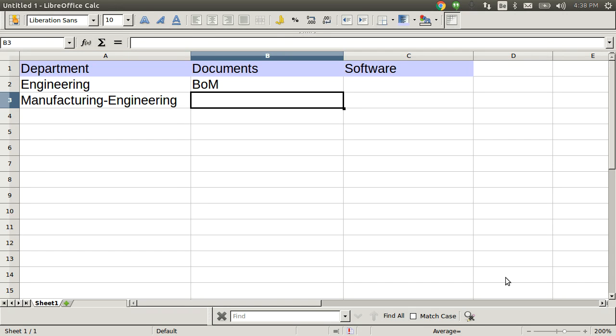Those guys are responsible to design the manufacturing line. So once we have the plan, we know how to build the piece. We have a department that has to buy the machine, set up the machine environment, and decide how the worker will work. First, they have to do the first operation, second operation, third operation. So they mostly are responsible for routing. That's the list of operations to manufacture a specific product.